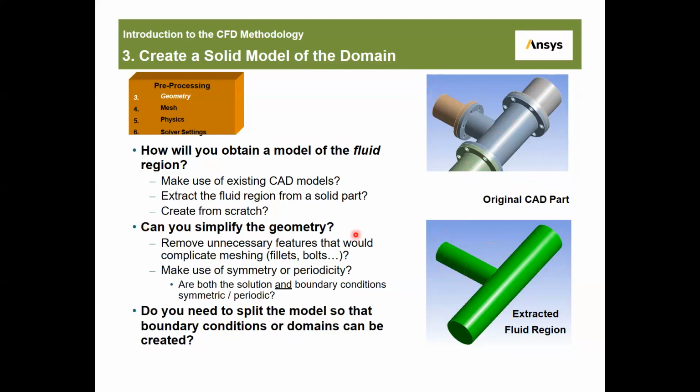Can you simplify the geometry? Remove unnecessary features that would complicate meshing, for example fillets and bolts. Instead of drawing holes and everything, we just draw a simple tube.